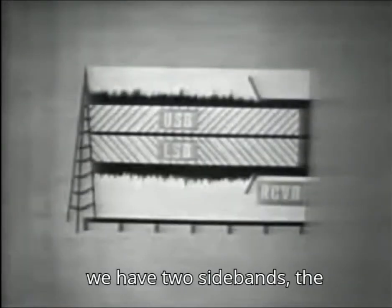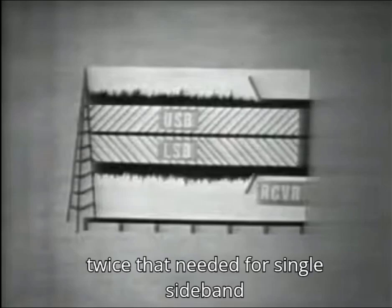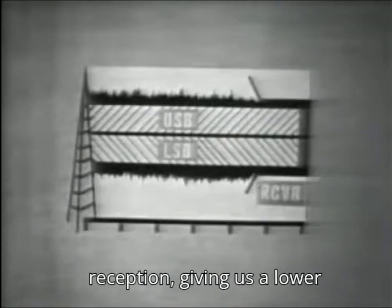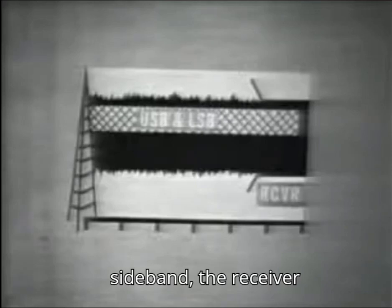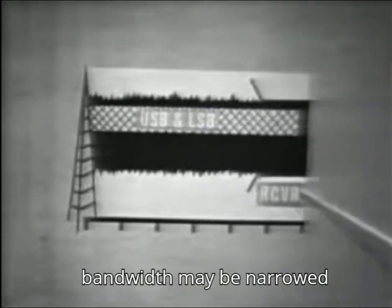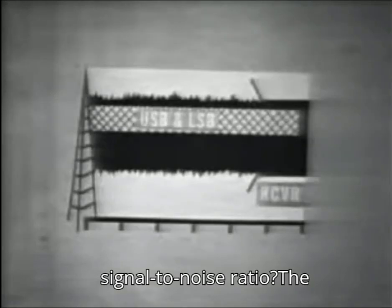When we have 2 sidebands, the receiver bandwidth required is twice that needed for single sideband reception, giving us a lower signal-to-noise ratio. But now that we have eliminated one sideband, the receiver bandwidth may be narrowed considerably. And now what happens to the signal-to-noise ratio?